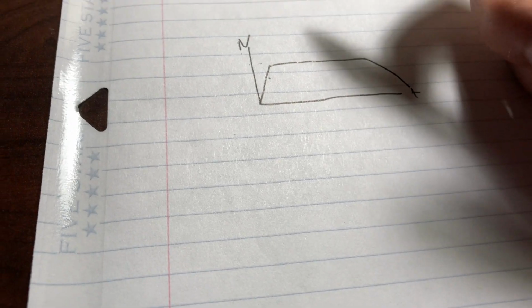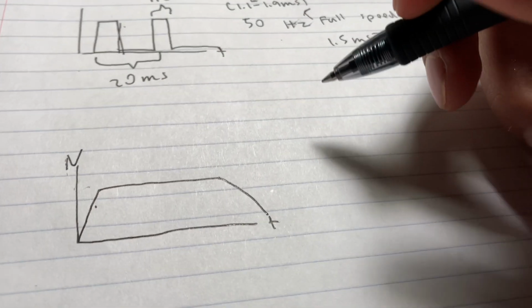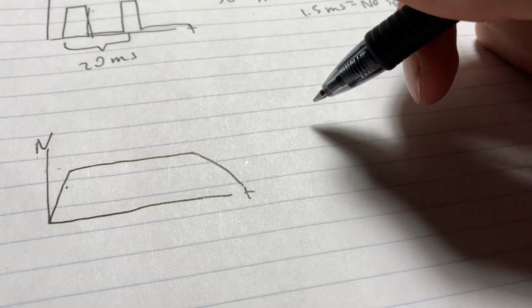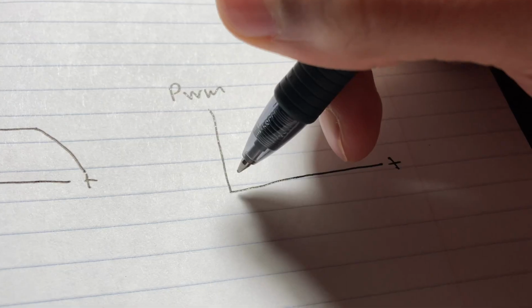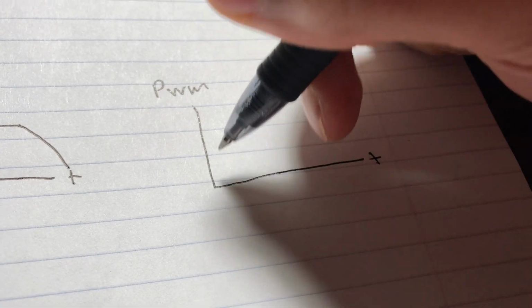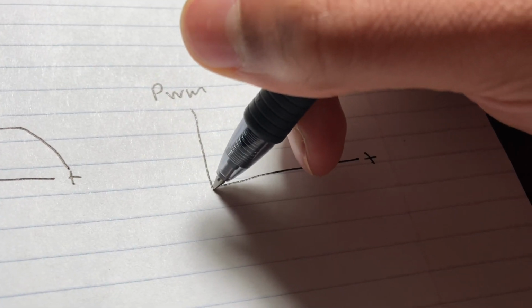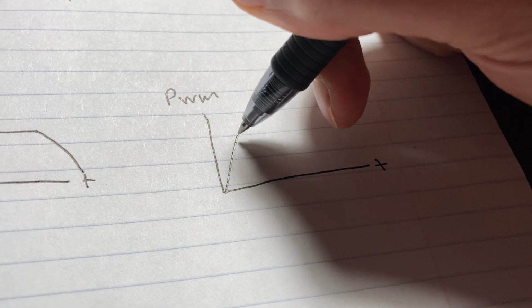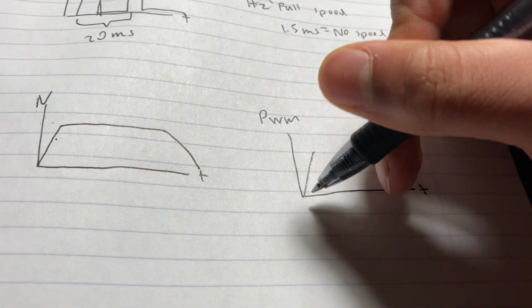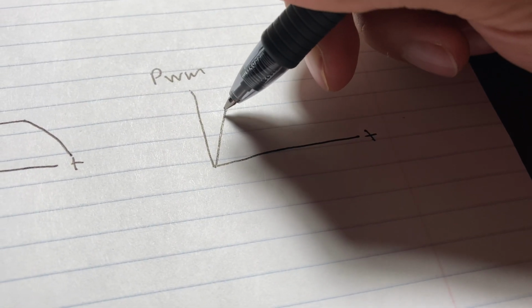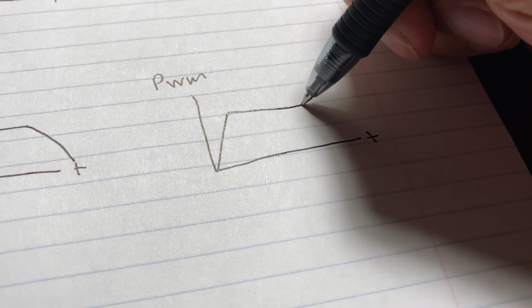Which is unlike robot tour, for example, where you do have to have your motions in terms of time in addition to distance. First, let's look at our PWM versus time graph. What's going to happen is that this should be diagonal on the way up, because the PWM signal controls the velocity of the motor. Now we're going to reach a full speed section, at which point it's going to be horizontal.